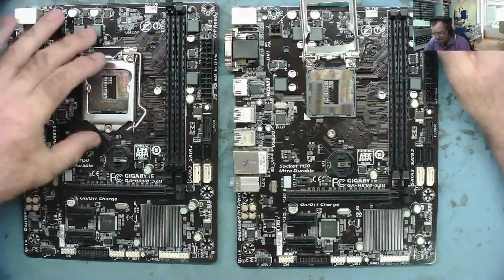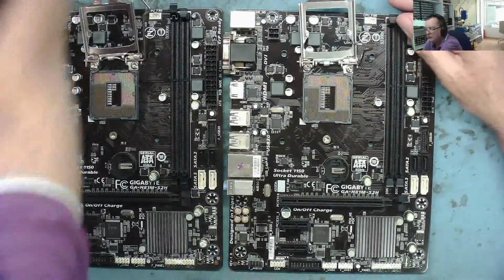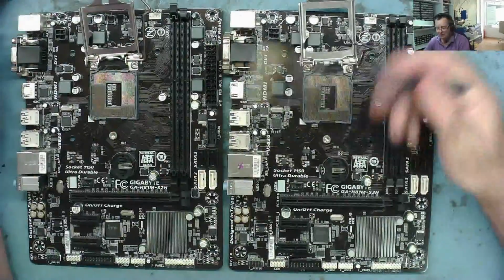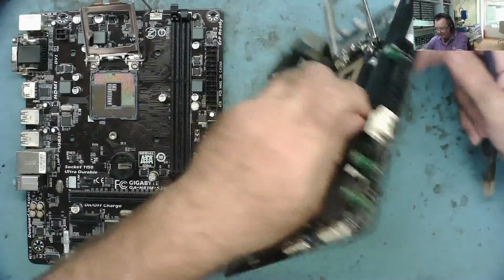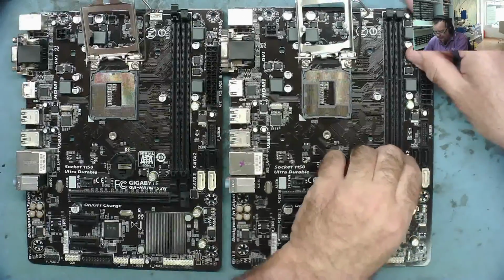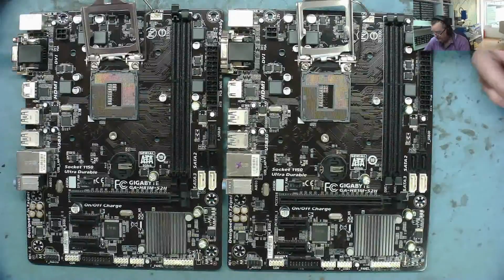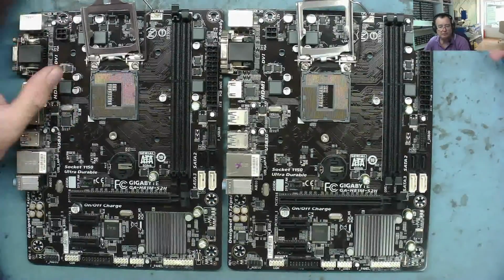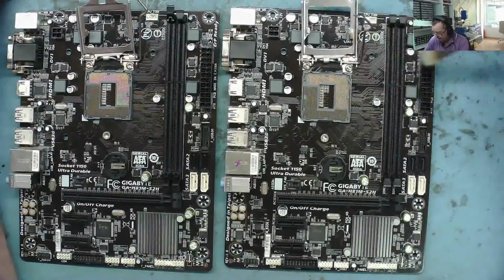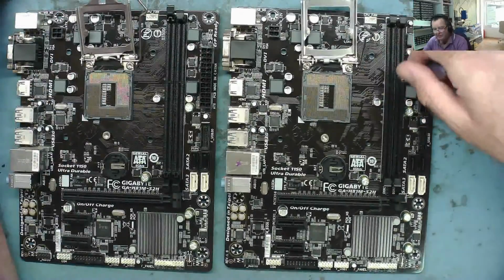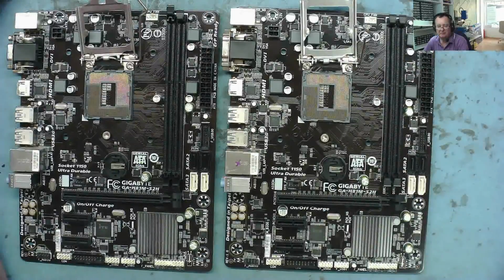But yesterday I put both of these in the sink with soap and water and a soft paintbrush, and I cleaned all the dirt off them really. So these are much cleaner now, both sides. So we're ready now to test this one again and see if it's still not working. I've got the other one which I can hopefully use as a comparison between the two if we need to do that. So let's put our known good CPU on this one, and we'll leave it without RAM and see if it bleeps when it boots up, and then we'll take it from there.